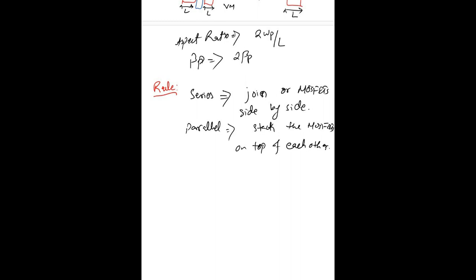So now we have combined different circuits to get a thicker MOSFET, or we can say a MOSFET with different transconductance or different width. So the equivalent circuit of the NAND gate can be replaced by a circuit shown here, an inverter circuit that has different aspect ratios.